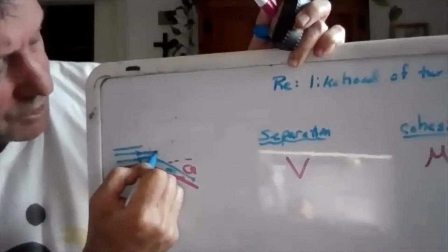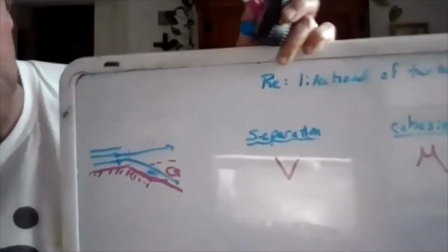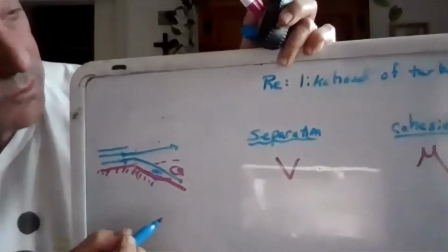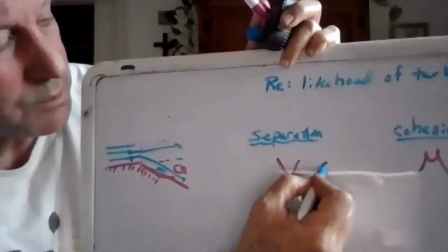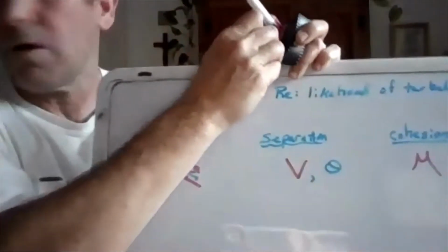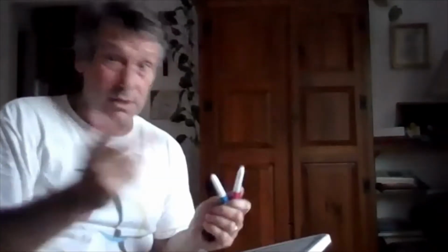And then this fluid is going to follow Newton's first law. A fluid tends to go in a straight line motion, and we could get separation in this case, and then we'll get that swirling. So another factor in there would be something to do with theta, how big the turn is. All right, so for every geometry out there, there's some sort of intuition: what about this geometry makes it more likely that we're going to get separation? And from that come some parameters that we combine together in a single number and calculate to determine the likelihood of turbulence.